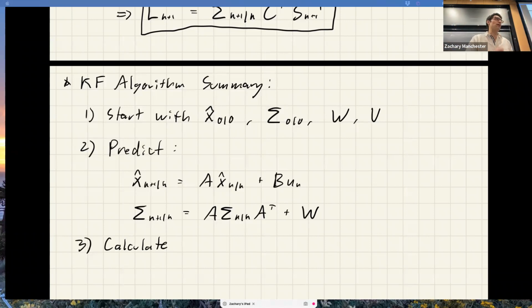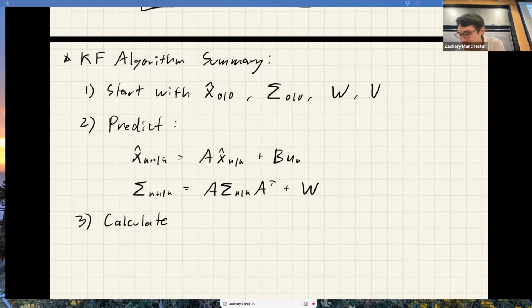It generally works okay. That's the standard thing, but there's a whole literature on nonlinear extensions: the unscented Kalman filter, iterated Kalman filters, particle filters, Gaussian mixture filters, an insane literature. But the most basic idea is the extended Kalman filter, and that is the first thing to try. If that works for you, then do that.